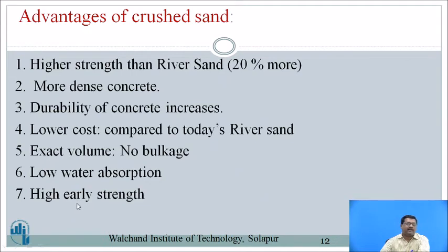In crushed sand, definitely we will get high early strength in 3 and 7 days. Shrinkage was the basic issue in earlier days, and micro cracks are always there in the river sand, but these micro cracks are reduced by a substantial amount in the crushed sand concrete.